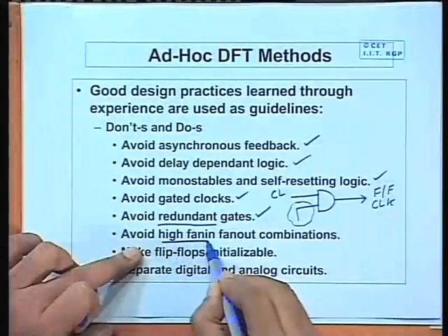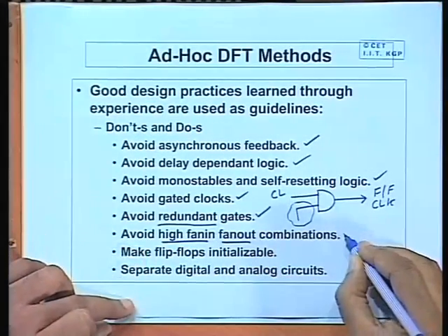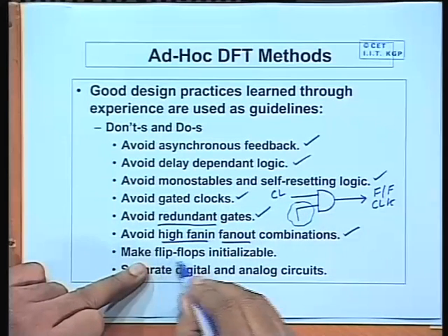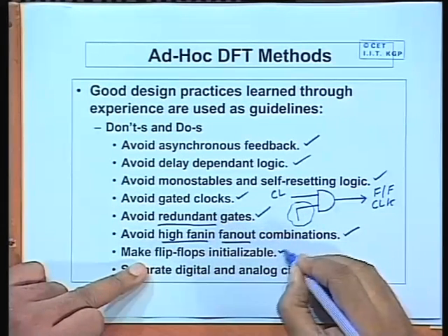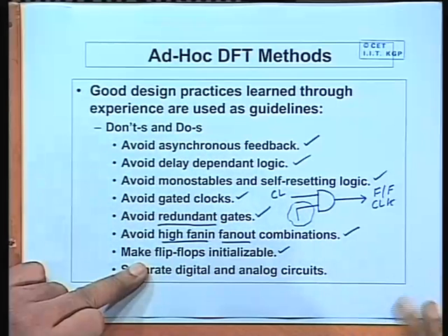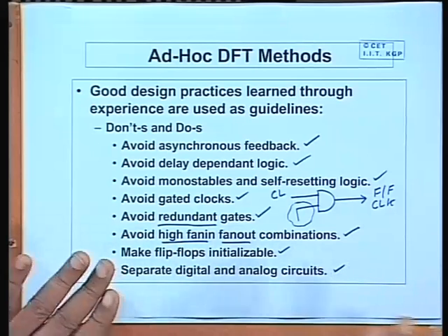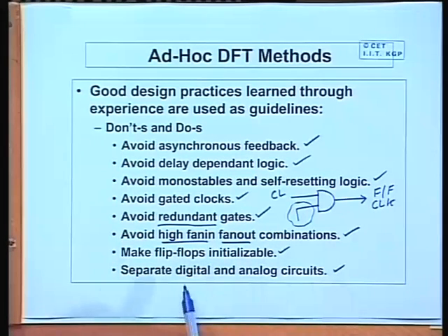Do not use high fan in or high fan out, because these are not good in terms of circuit performance and also reliability. All the flip flops should be initializable externally with relatively less effort. If you have a mixed signal design where both analog and digital circuits are on the same chip, you try to separate them out into disjoint areas of the chip. Do not let the analog circuit and digital circuit interact with each other closely and result in unpredictable behavior.